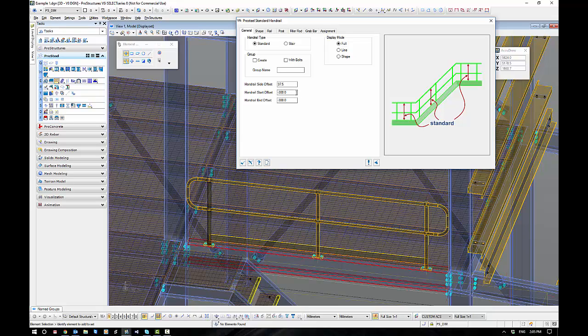Okay, you can see at the moment that I've got a -300 offset each side, and I want to pull that in a little bit. So let's move that to 360, and I'm going to apply the changes, and you can see it moves straight in. So like I said, this is parametric. You think of it like an automatic connection. It updates as you tell it to update.